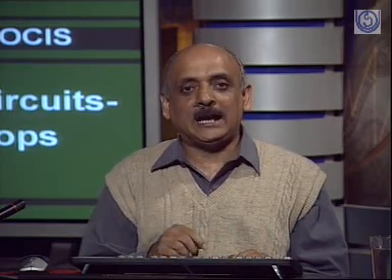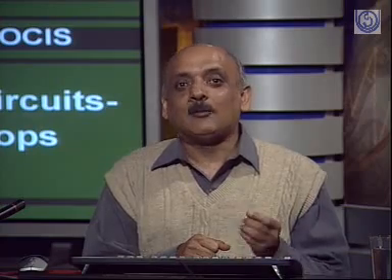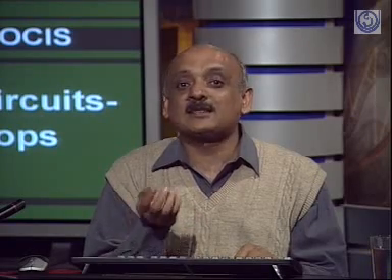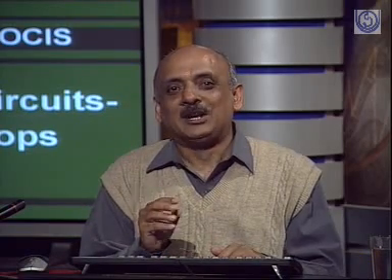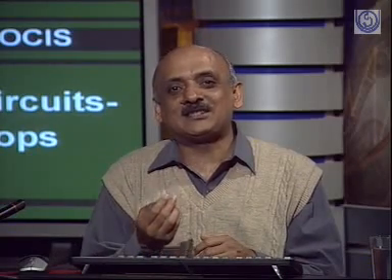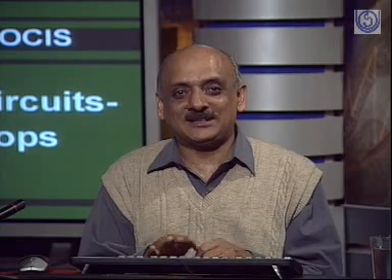So in this particular session, I have tried to define the very basics about sequential circuits. My basic objective initially was to explain what the basic issues are as far as sequential circuits are concerned, and where you need a sequential circuit. Then we talked about one of the major components of any sequential circuit, which can be utilized as the storage element: the flip-flop. In the flip-flop, we talked about two things. One, how exactly it functions, and the characteristic table for its functioning. And the second, the excitation table for the flip-flops. The use of the excitation table is going to be when we utilize the flip-flop for design purposes. So for the time being, I wind up this session with this statement.